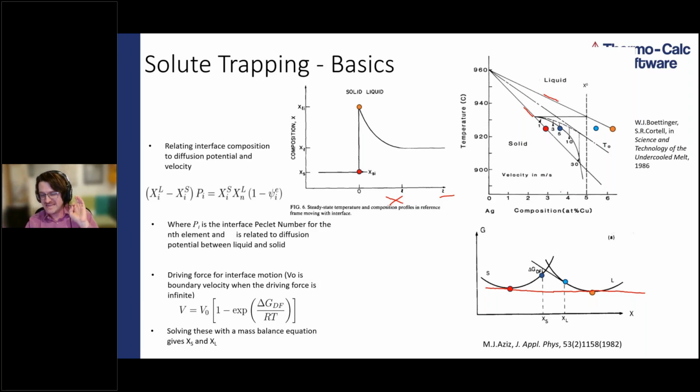So if we were to solidify infinitely fast, move that laser at 1,000 meters per second, the liquid would just turn into a solid. There would be no segregation of elements. We would just instantly solidify, right? And that actually would happen at the T0 point, which is this point where the Gibbs energy curves cross each other, where they're equal. And that T0 line, it can be drawn on the phase diagram, typically bisects the phase field like is shown here.